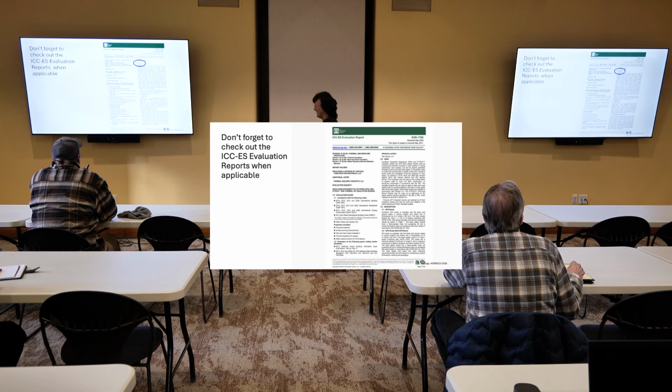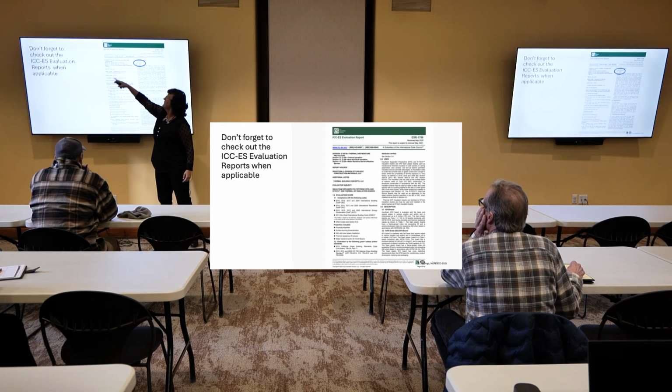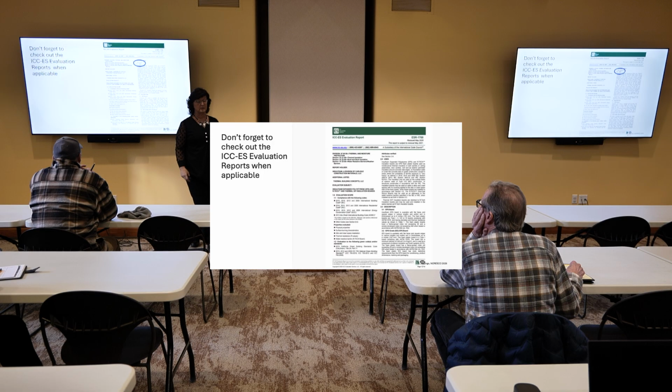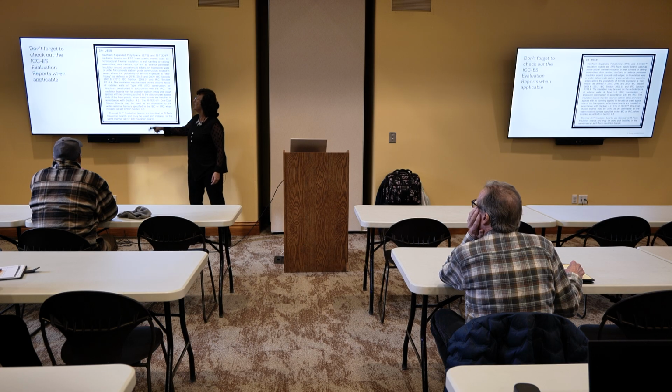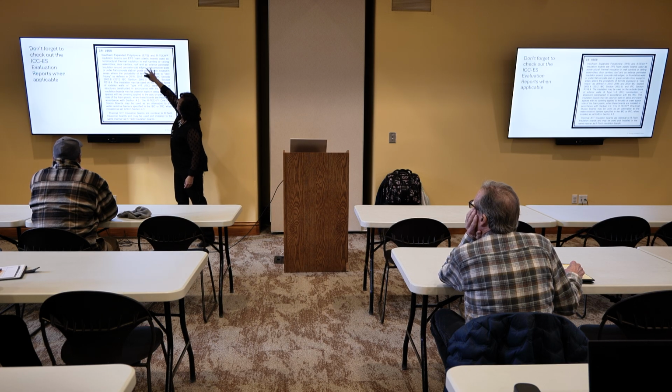Can I use it as those things? They're evaluating it for those three: insulation, roof deck insulation, and a thermal and water resistive barrier. So here are my uses. If I blow that up, I can have it for cavities, on the roof, for slab edge, certain things. It meets the code.